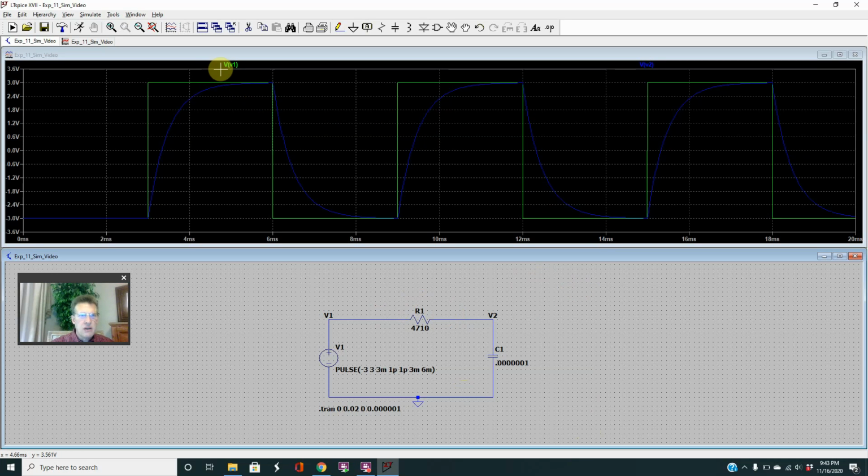So up here we've got our legend in green. That's the V1 voltage across our power source. So that makes perfect sense. And then this should look really familiar if you've watched the video. This should be very familiar to what we're seeing, which is the exponential decay, and then the exponential rise back and forth across the capacitor due to the transients.